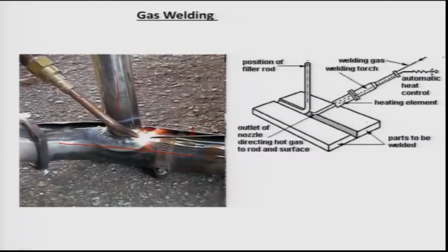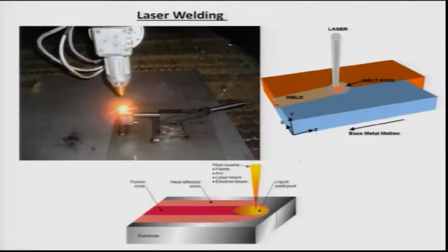Again, because welding is happening only in a small region, the bulk of these pieces remains solid, therefore there is an enormous number of heterogeneous nucleation sites present on the surface. So the only issue here is how the nucleating solids grow into the liquid. So that's the basic aspect.